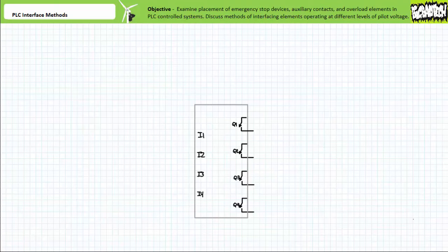You will recall that the fundamental operational principle of ladder logic is the establishment of two different levels of power: pilot and primary. Pilot or control signals are ordinarily low current, low voltage, low power signals that solely coordinate the action of interface elements like contactors and solenoid operated valves. Primary signals, in contrast, are high current, high voltage electrical or high flow, high pressure hydraulic or pneumatic input that does the actual work.